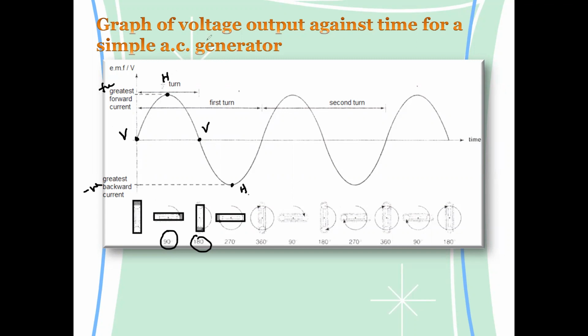And when the coil is exactly vertical back again, there is no change in the magnetic field, so there is no induced EMF. And this is the position vertical back again. This one complete rotation involved 360 degrees. So this is known as one cycle of AC, in which we'll have positive and negative voltages. If I use a stronger magnet or more turns of wire, what will happen?